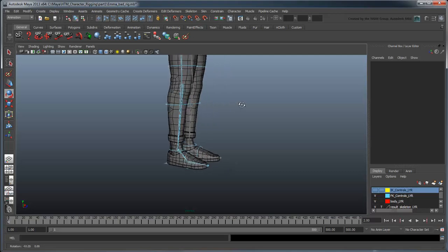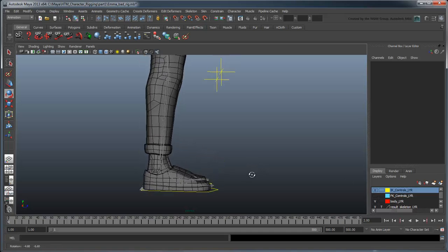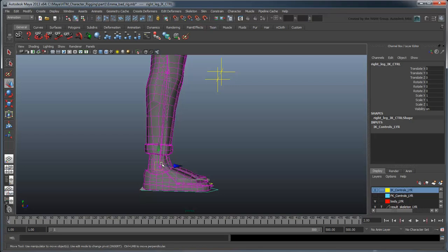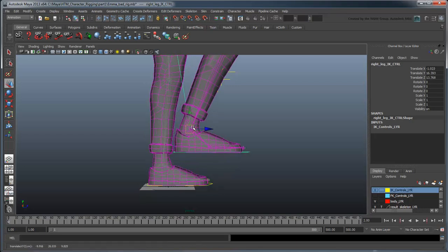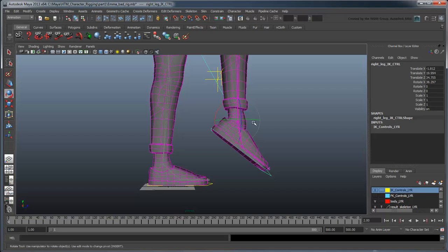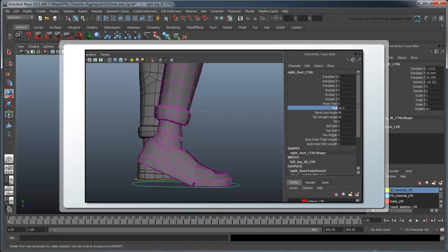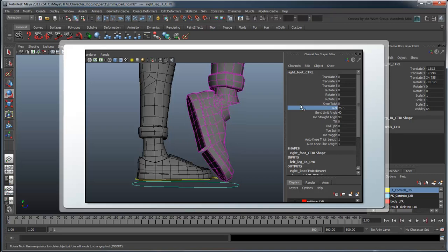Turning our attention from the hand to the foot, imagine trying to animate a simple walk cycle. Because the foot IK control's pivot is at the ankle and not at the ball or toe, we'd have to continually raise and rotate the foot for each keyframe. Again, this would make a tedious and choppy process for the animator. Instead, a rig should provide them with custom attributes to control the foot's range of motion, like foot roll and toe lift.